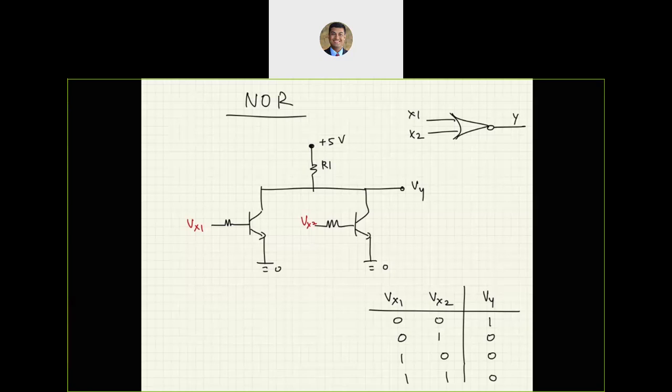But for the discussion on logic circuitry, we are going to assume that the transistor is operating in those two extreme cases, when it is on and when it is off, meaning it is either in the cutoff region or in the saturation region. So we are ignoring the active region of the transistor in all these conversations.